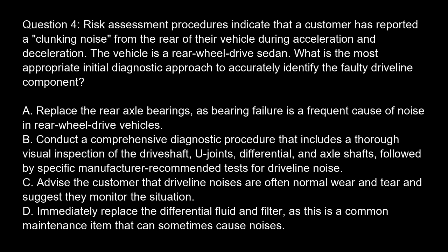Option A. Replace the rear axle bearings, as bearing failure is a frequent cause of noise in rear-wheel drive vehicles. Option B. Conduct a comprehensive diagnostic procedure that includes a thorough visual inspection of the drive shaft, U-joints, differential and axle shafts, followed by specific manufacturer-recommended tests for driveline noise. Option C. Advise the customer that driveline noises are often normal wear and tear and suggest they monitor the situation. Option D. Immediately replace the differential fluid and filter, as this is a common maintenance item that can sometimes cause noises.